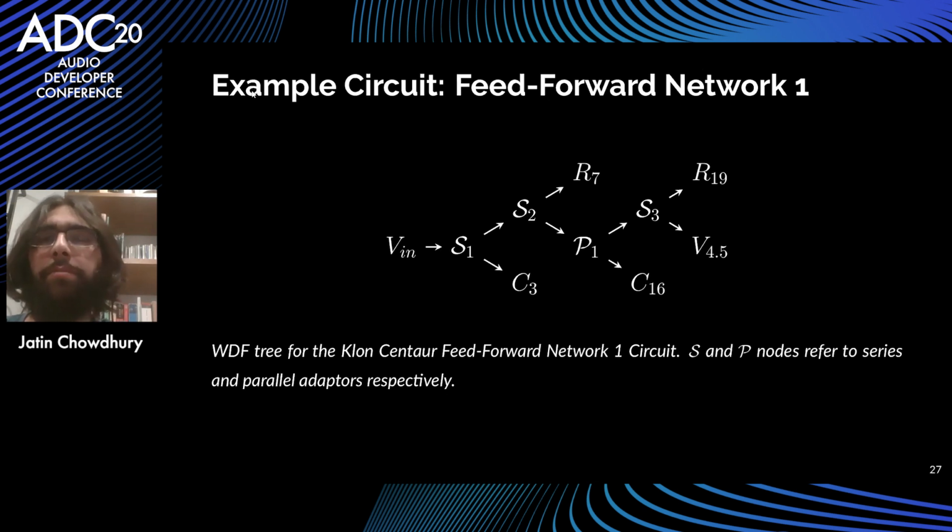But this is a great question because when you're formulating this binary connection tree, it's very important to think about what component gets put at the root of the tree, which is here. So kind of what I mentioned with having that free parameter. Whenever you have a series junction like this, you get one free parameter that you can choose, one port resistance that you can choose.